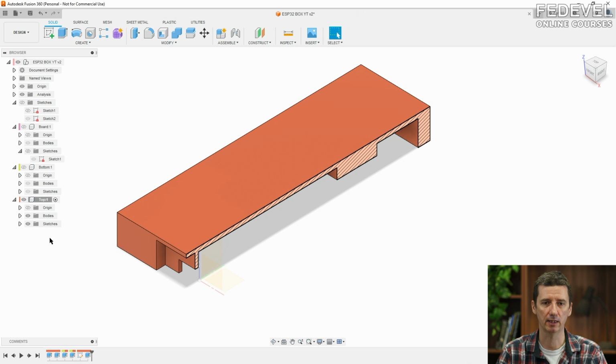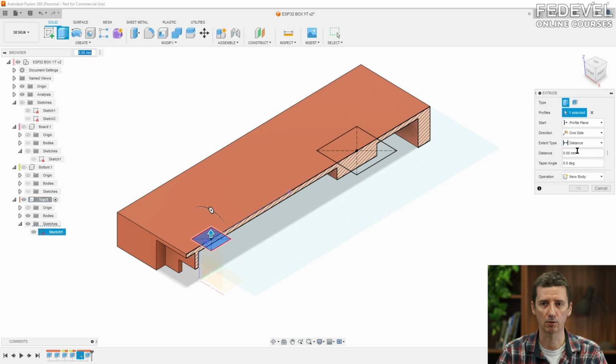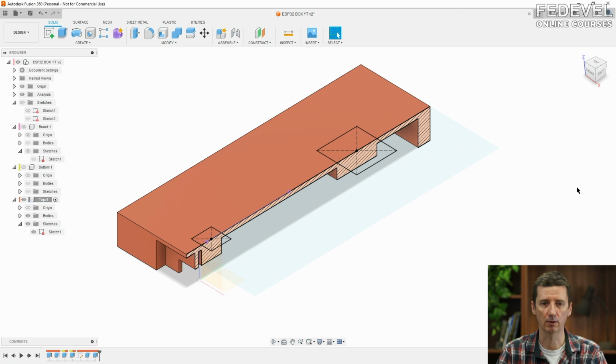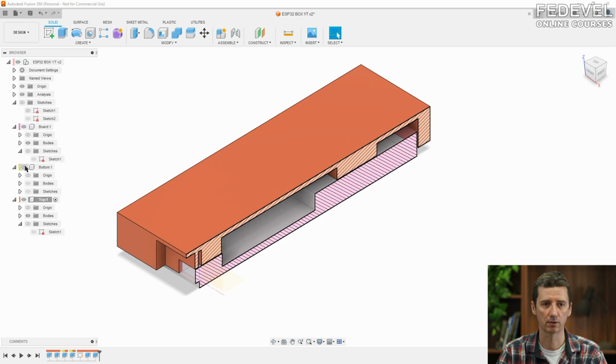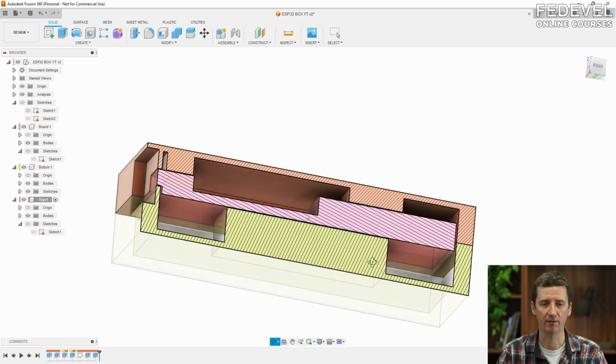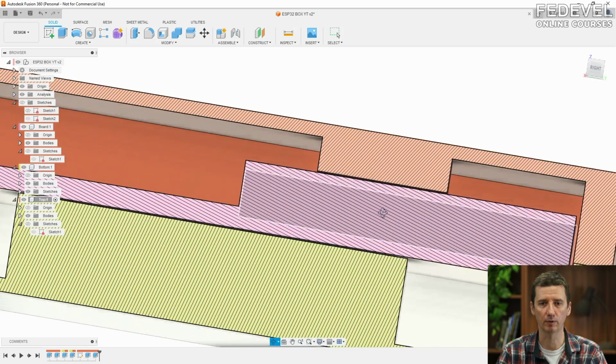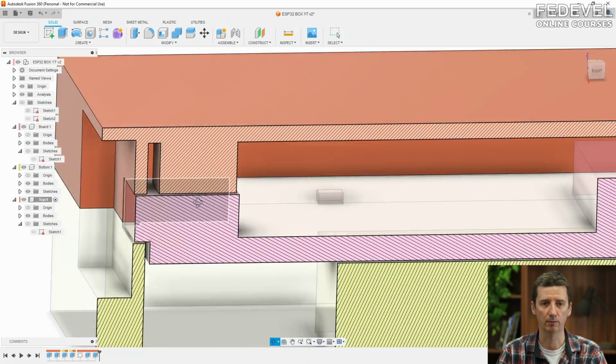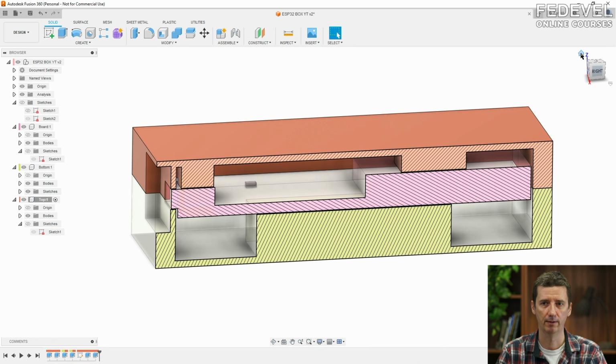Okay. Do very similar also for the USB. So select it, use extrude up to minus box top height. Be sure you select join, and plus USB height plus tolerance small. Okay. Double check if it looks correct. Perfect. So now the PCB is not going to float inside of the box. It has support from the bottom and from the top. Perfect.